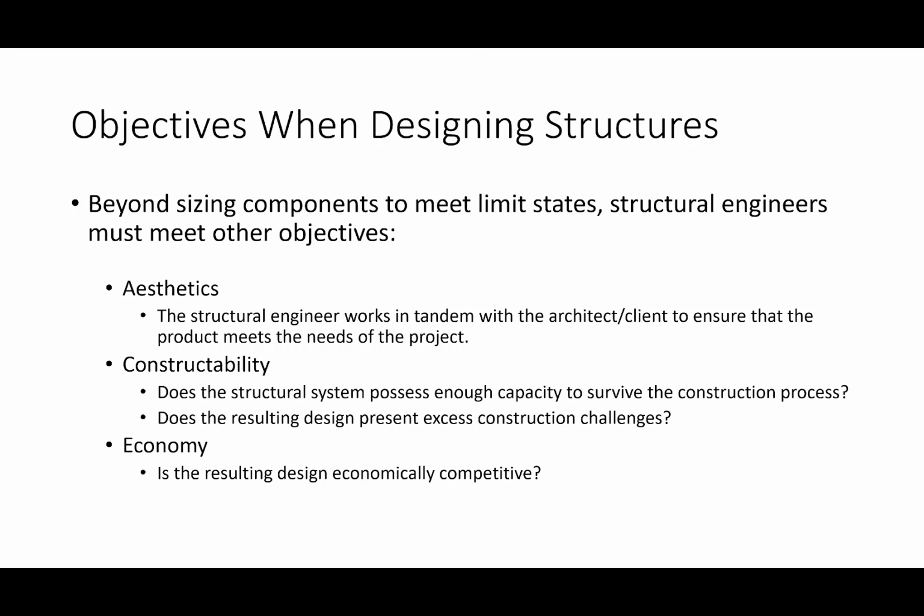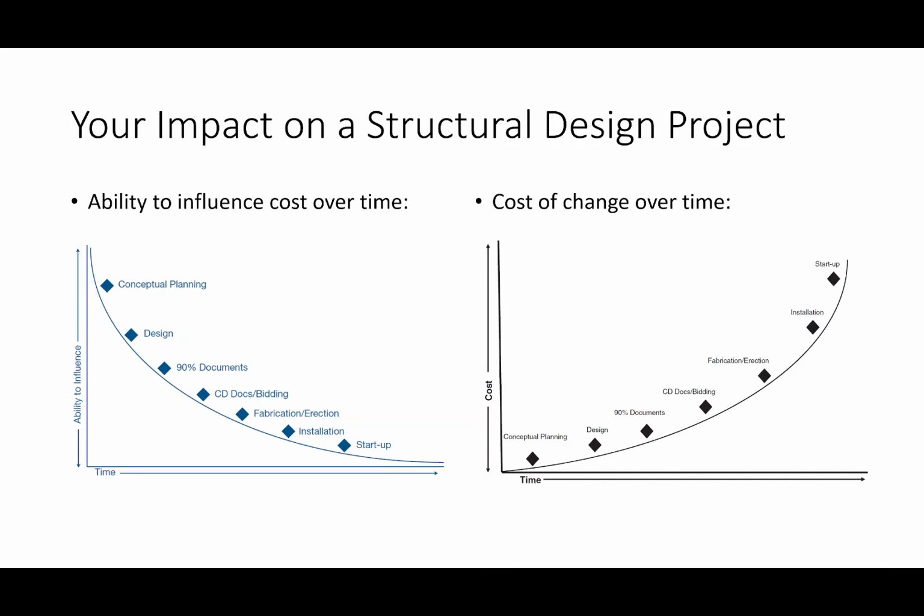One thing that's also pretty interesting is that sometimes the loads you see during construction are actually worse than the loads during the final finish stage. Actually, the highest stresses and design considerations can be during construction. So does the structural system possess enough capacity to even survive the construction process? And then obviously, economy as well.